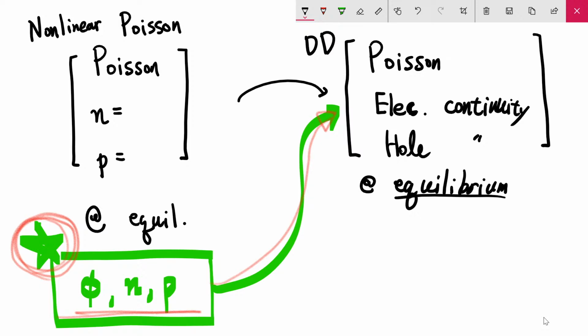When you evaluate it, due to numerical error, your residue vector cannot be exactly a null vector. Of course, there will be a small number. However, the small number is really small, so you will have just a negligible update vector, and that will automatically guarantee the convergence of your first Newton iteration.